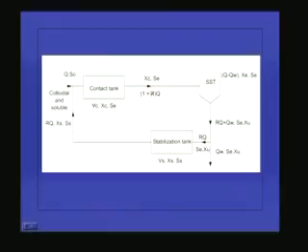So, this is the schematic of a contact stabilization tank. The wastewater is coming with a flow rate of Q and a BOD of S0, and this contains both colloidal and soluble matter. This is the contact tank with a volume of Vc, biomass concentration of Xc and BOD of Sc, because here the soluble BOD is changing from S0 to Sc.